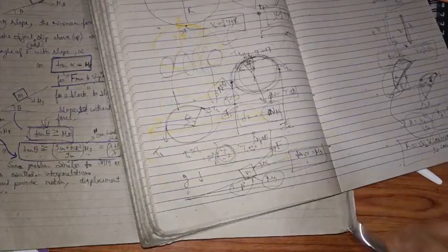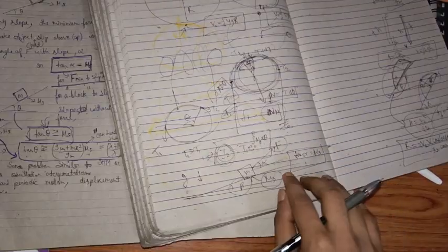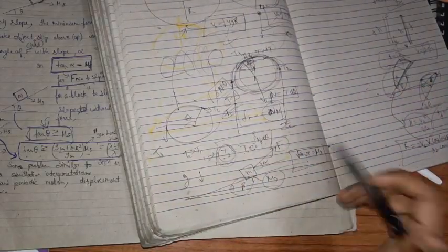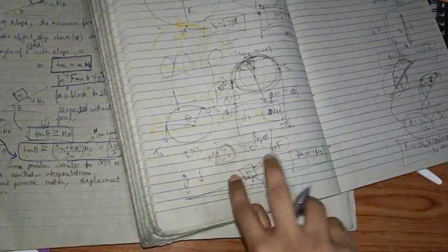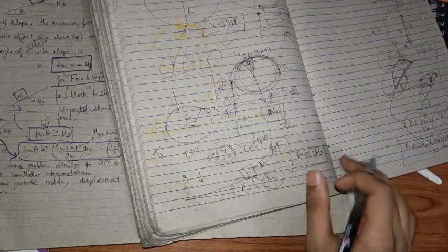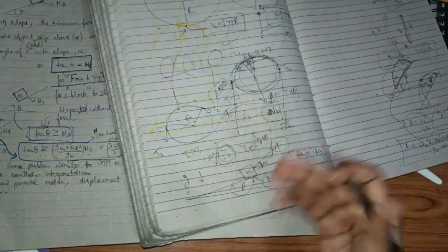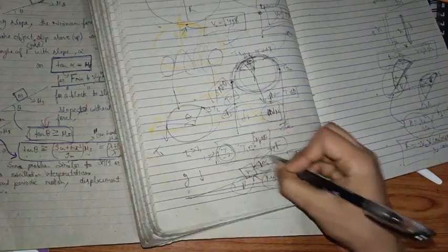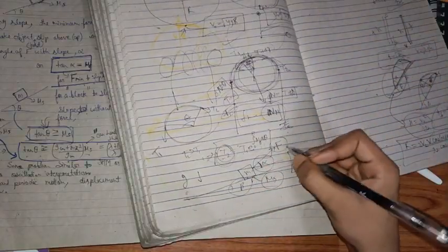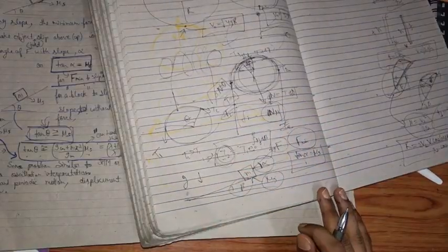So tan alpha is equal to mu s, and that is the minimum value for it to slip; as alpha becomes greater, it starts slipping. Sorry, this is the case for the minimum force required for it to slip. So at this angle the force is minimum for it to slip. It does not mean that if you apply force at any other angle it will slip. No, it will not slip, because that is the angle at which the force is minimum. So F minimum occurs at this angle, and changing the angle will not make it slip if the minimum force is applied.